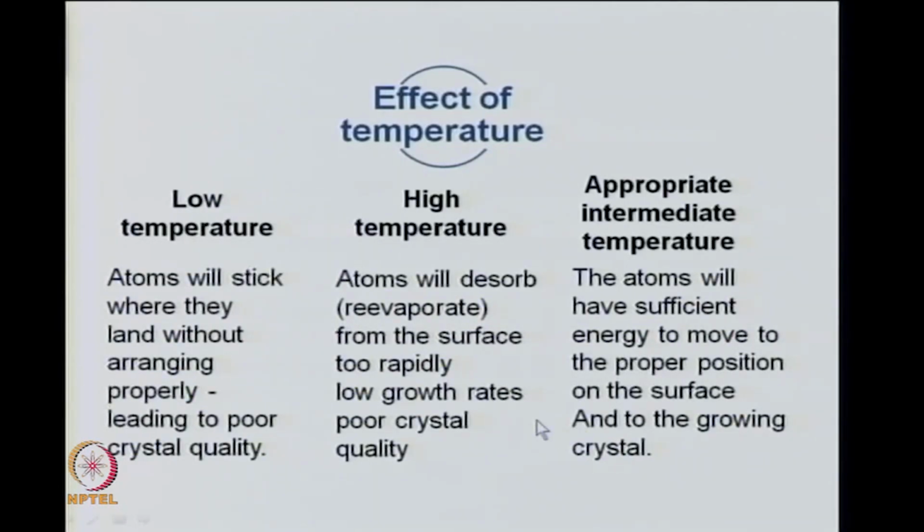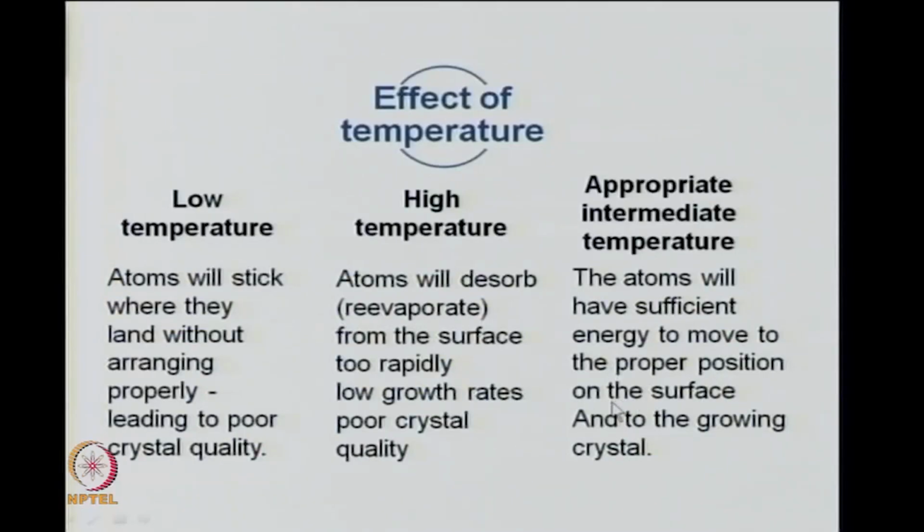So, you need to optimize the temperature such that you do not have a very low temperature with the atoms sticking wherever they fall, or a very high temperature where the atoms adsorb and desorb immediately or re-evaporate. You want a temperature where the atom adsorbs and then has some energy to move around to find the proper position which has a minimum in energy on the surface, and hence will add to the growing crystal and to the growing epitaxial layer.